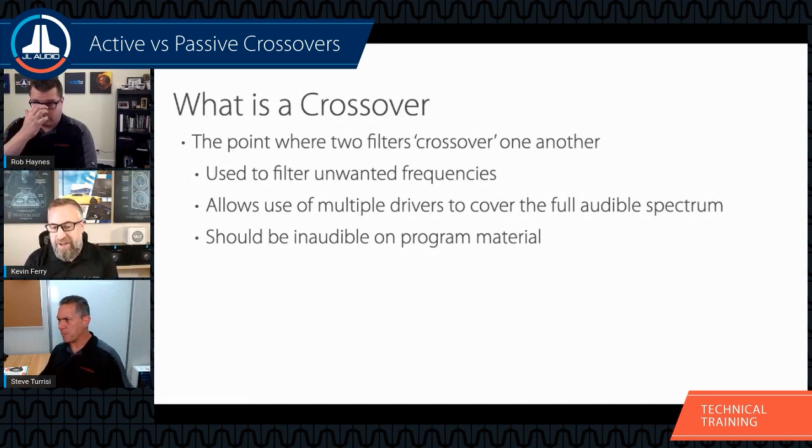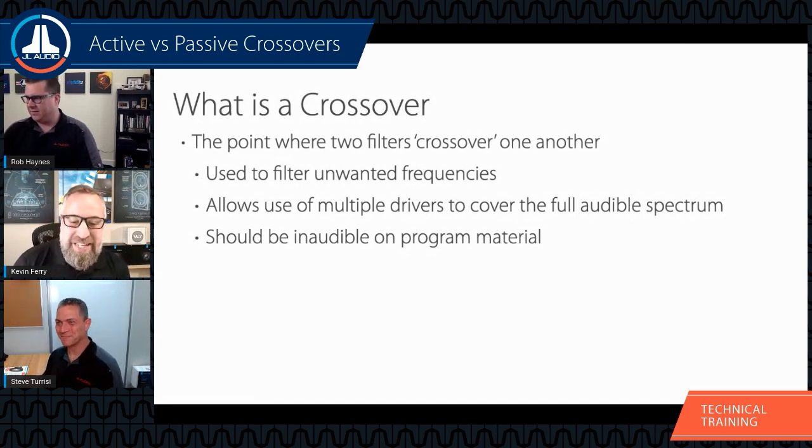So for instance, if we have a tweeter, a tweeter really can't play 200 hertz well, at least not for very long. It might play it once. So we have a dedicated mid-bass driver to pick up and play those frequencies. We are going to get all of them. We just want to make sure that each speaker is playing in its effective range.